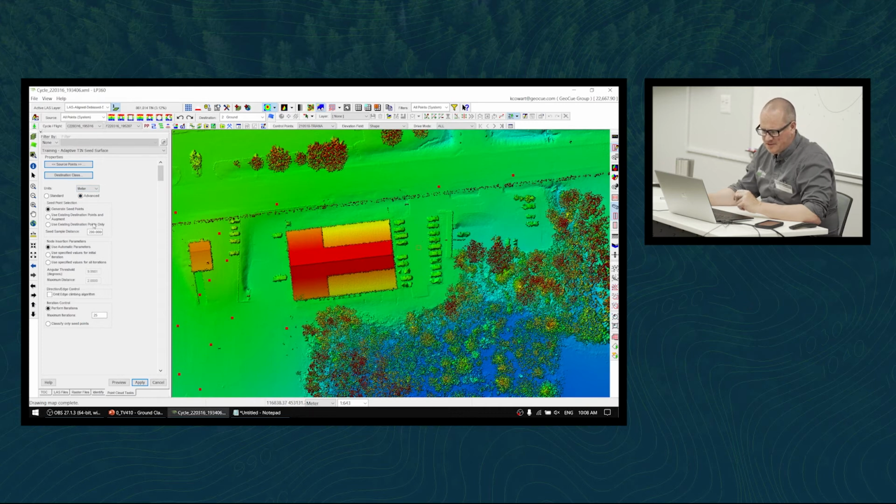And let's go through some of these other options. Units set to meters, advance. We do want to hit generate seed points on this one. For the seed sample distance, I like to use 3. Let's use 3 today. So that's 3 meters. And of course, the values for all these are completely up to the user, and you should experiment with them and learn how they work and how they'll give you different results.